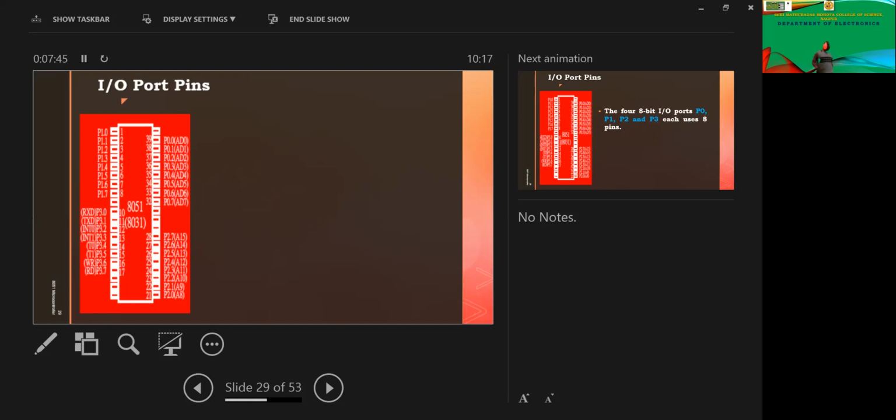So whether the microcontroller needs to write a program or whether the microcontroller is reading a program, that is being determined by these two pins, P3.6 and P3.7. Again, what I mean to tell you is that these pins are used doubly. When we are programming it, these pins work like this, whereas when we have filled the program, they are used as plain ports, right? So I guess this much I need to tell you about the ports.